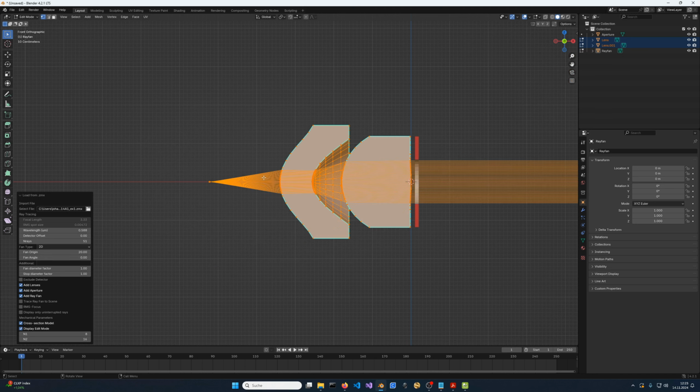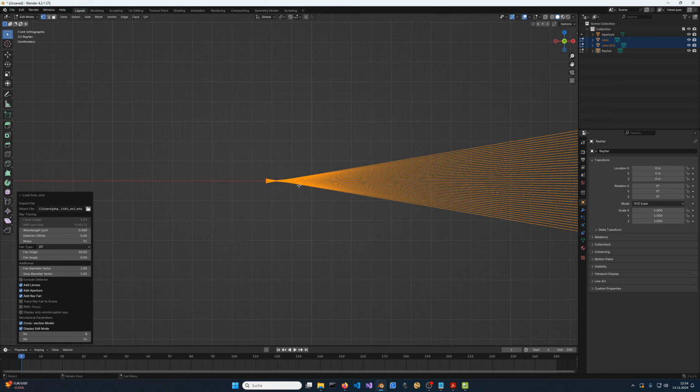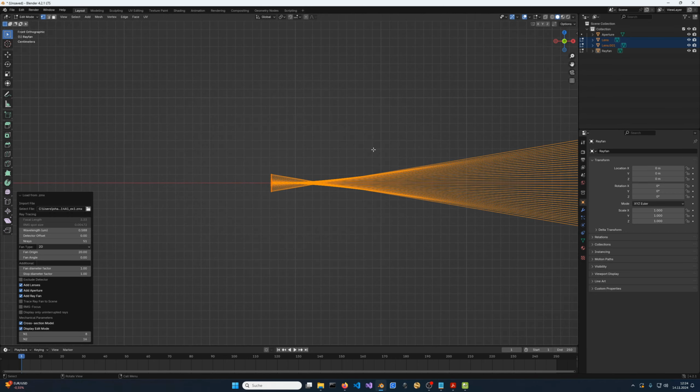Now, this lens is worth inspecting a little closer for two purposes. First, cross-checking that the implementation of aspheric surfaces, so the sequential ray tracing, is actually correct, and also understanding a little bit more about how lenses are typically specified and the role of paraxial calculations in this. Because if for this on-axis beam at 0 degree angle, I zoom in, it again looks like the focus is not really chosen very well. So I've not activated the RMS focus option here, which would place the spot approximately in this location, which looks a lot better. Instead, this image plane comes directly from the zmx file, as it's specified there.